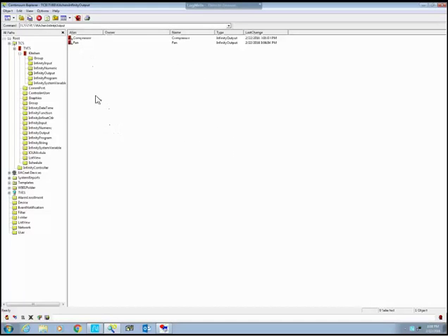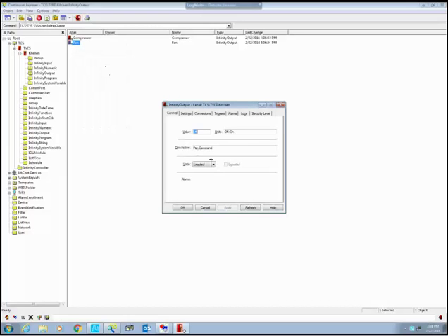2 outputs. Now to make these things do something, if you had something physically connected to them correctly, and you turned this on, applied it, and refreshed, that should physically make the point come on. That should make continuity between the common and the output terminal, whatever that is. It's just a switch. That's really all it is. And if you turn it off, it should go off.